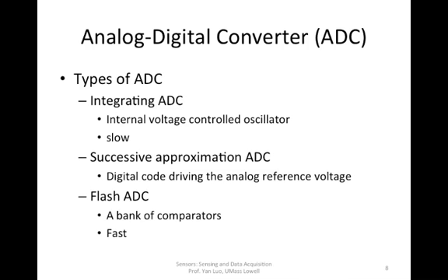Integrating ADC, internally it has an oscillator and an integrator. You will apply the input voltage to the integrator. Also, you can apply a reference voltage to the integrator.